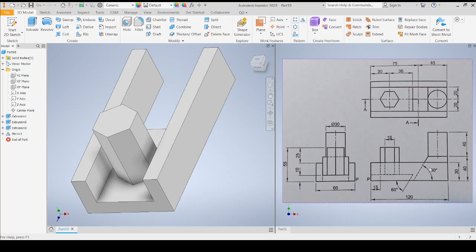We're gonna start off with this body, projecting it up. So as you can see, this body is going at a bit of an angle, which is 60 degrees. And then when you look at it from the top view, you can see that there's a circle, meaning that this right here, when you project it up, you get this circle. And then they give us the dimension, which is diameter 30.